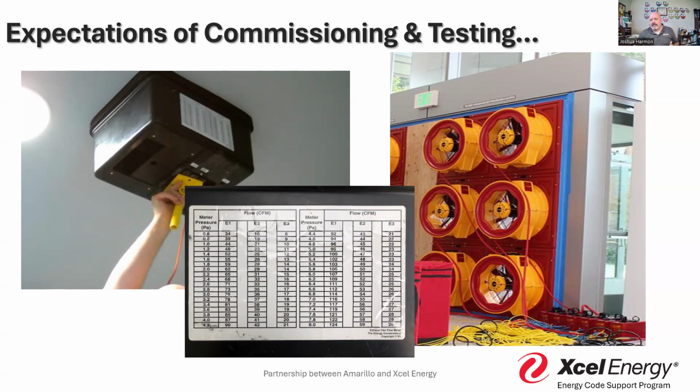So again, it's part of that relationship about how we look at the equipment and how it's going to operate. Here we got an example of one that's in a little bit larger facility. So again, you can add more blower door fans to the system in order to do a larger test. But if he's getting 35 CFMs of air leakage in a building of that size, he's within what the code would say is an allowable, most likely an allowable square footage.